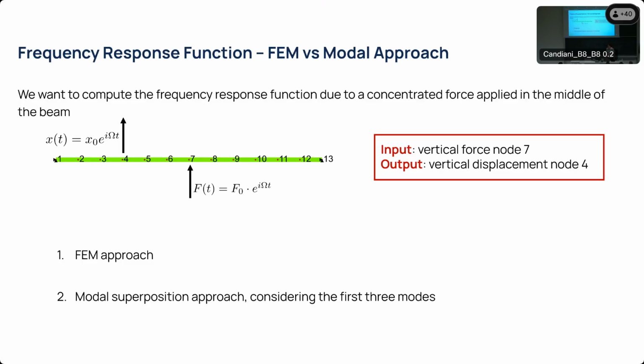In those cases, it is very wise to try reducing the dimension of your problem, because maybe you are not interested in the frequency range of the 2 kilometer bridge between 0 and 1 billion hertz. Maybe you are just interested in its first 3, 4 mode shapes.